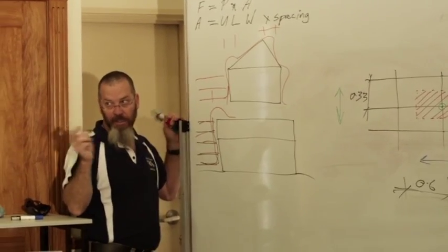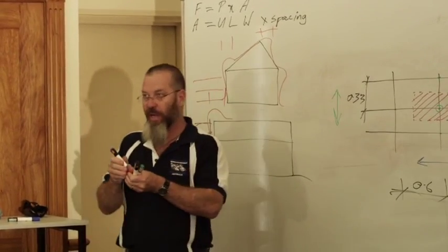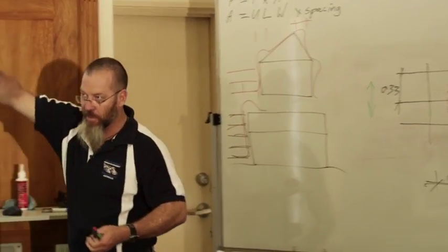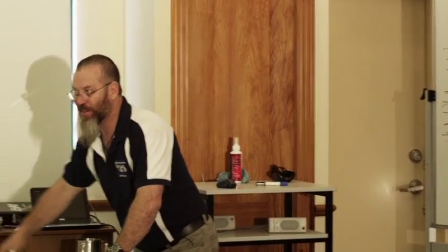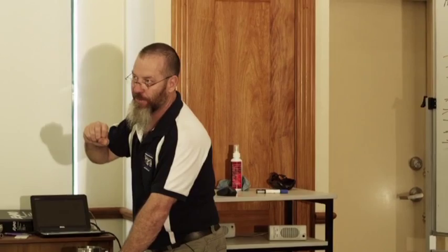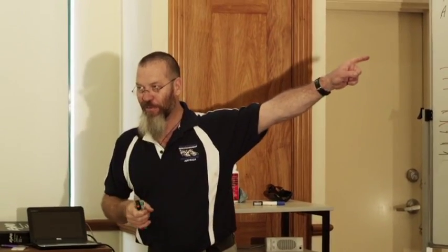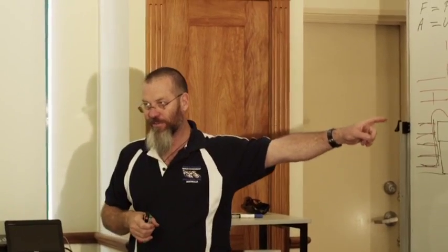And a hip would be exactly the same. As you've got the wind blowing over the side of the hip, it's going to create a Bernoulli on that. So that's what edges are. Edges aren't the fascia or the barge. They're also the ridge and the hips. Okay, you just got to kind of stick with the definition I give you back there at that other slide.